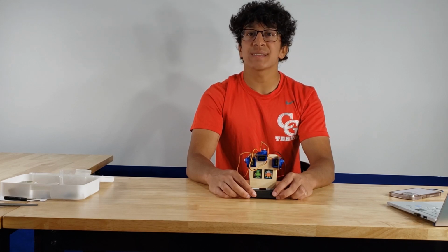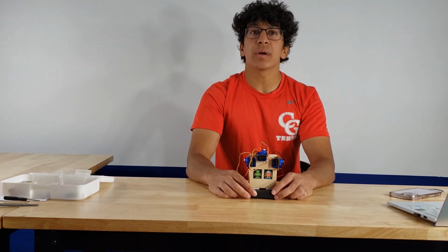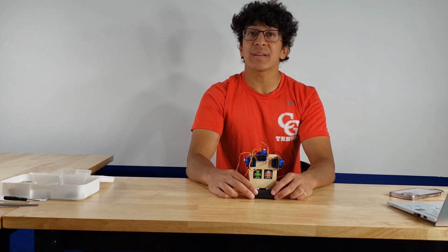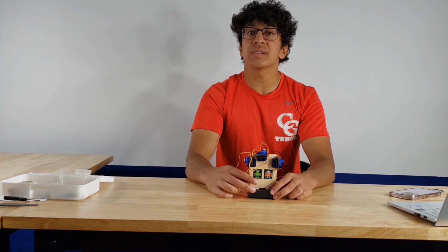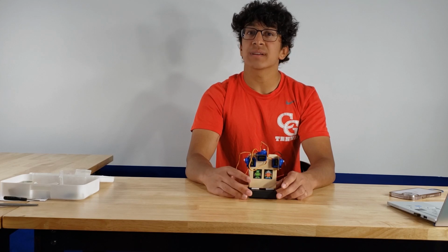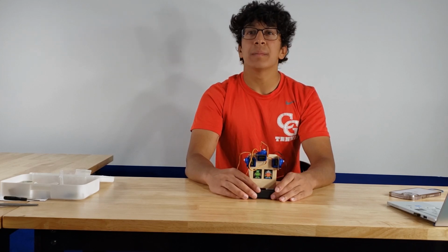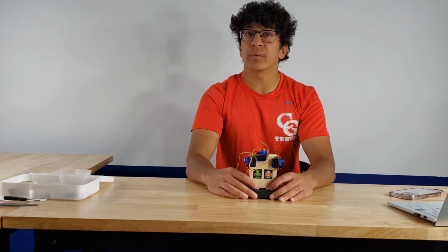Calibration is a process to bring the motors to a known position so that we can attach the arms and the head, and the program will know exactly how to position and make the movements correctly. Essentially, a calibration is a special purpose small program that we upload to the robot's memory and run to bring the motors to their known position. For example, 90 degrees. But how do we write the program and load that into the robot's memory?